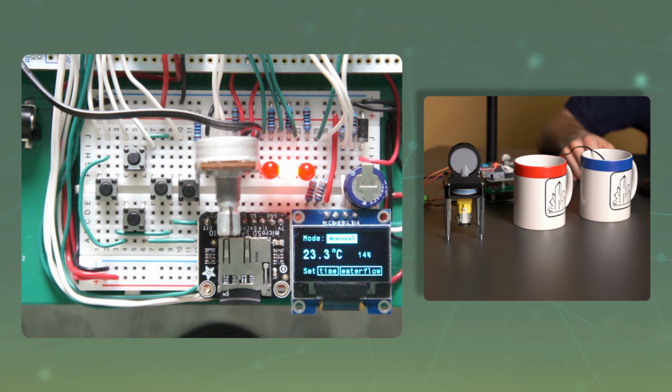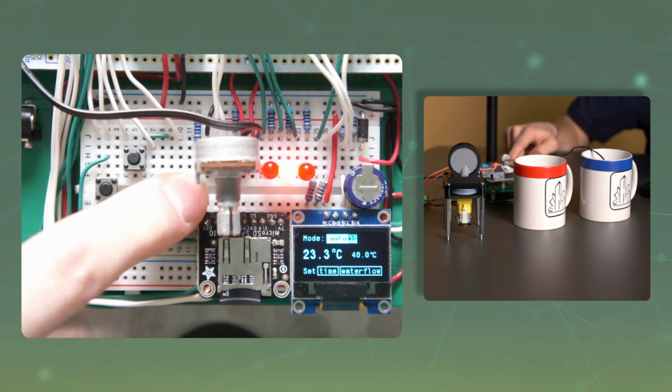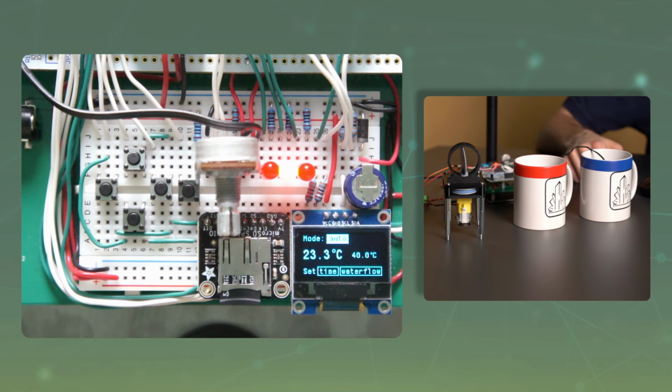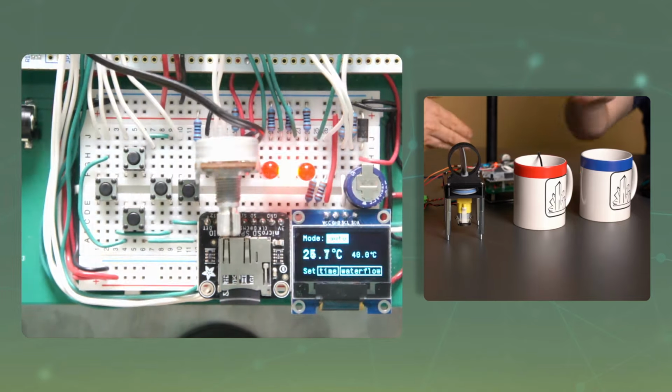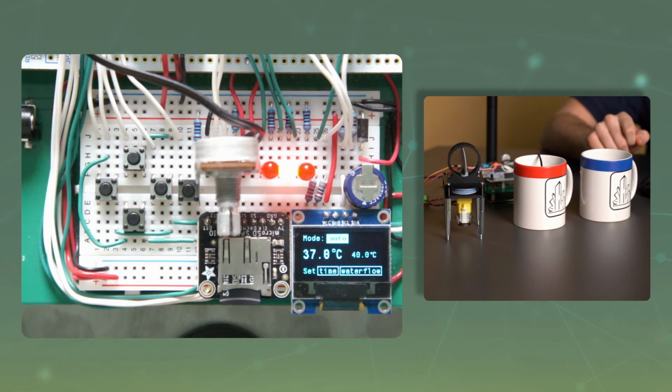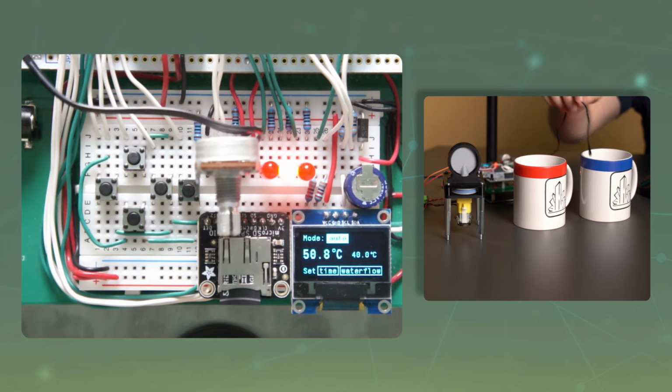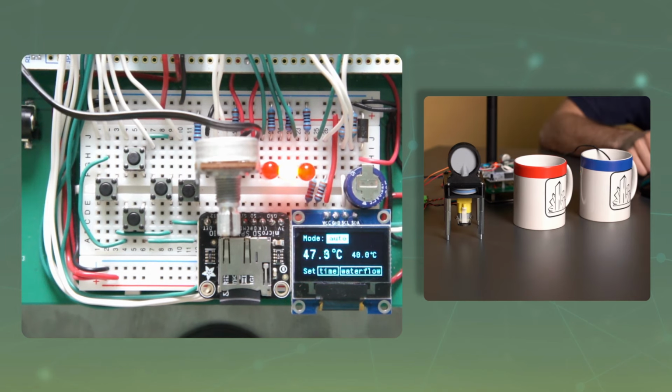Once we're done with that, the next step is to test the automatic mode. So we are switching to automatic mode. Since we have 40 degrees set in the program, and the sensor is only measuring 23 degrees, this means the hot water valve has to be fully open to heat the water in our shower. So let's simulate the water heating up in our shower. You can see the measured temperature rise, and as soon as it reaches 40 degrees, it starts to turn off the valve. And if we start to cool down the measured temperature, meaning our water during our shower is getting colder again, then around 40 degrees the valve will open, forcing our water to heat up.